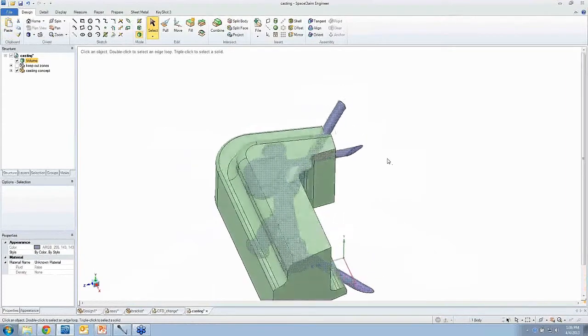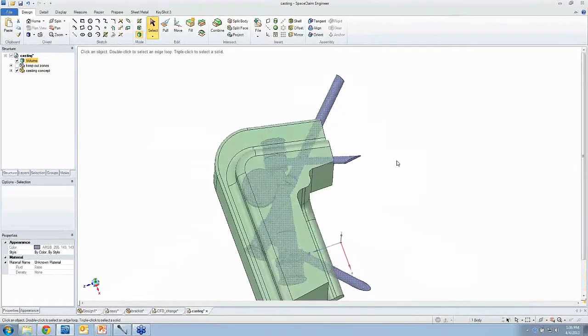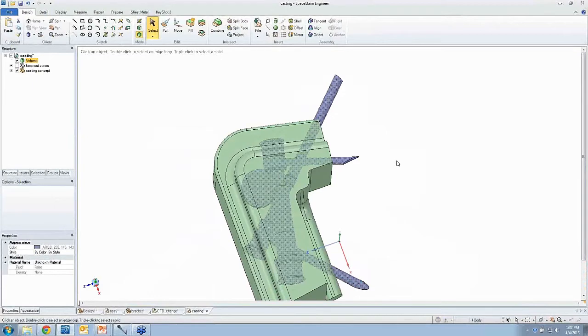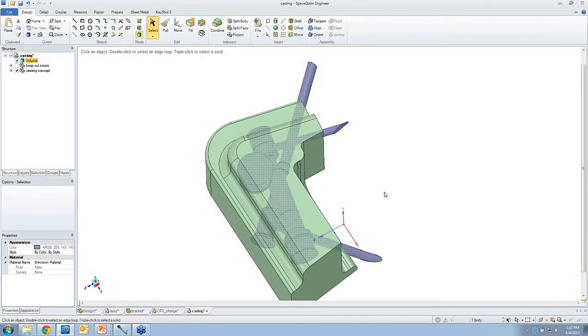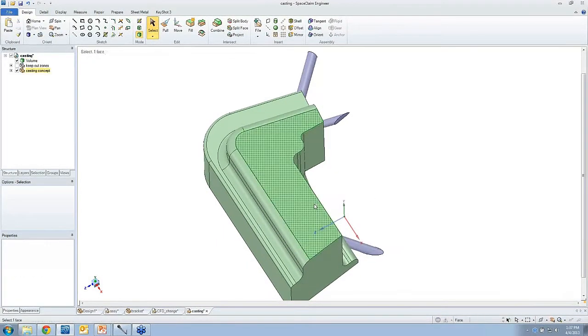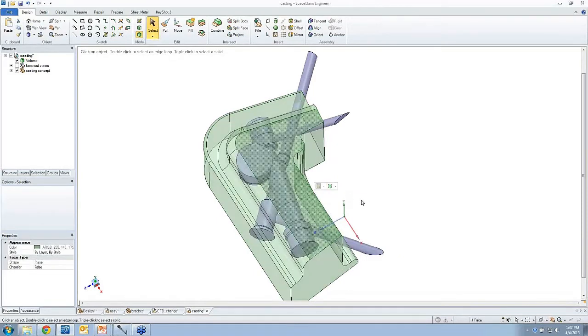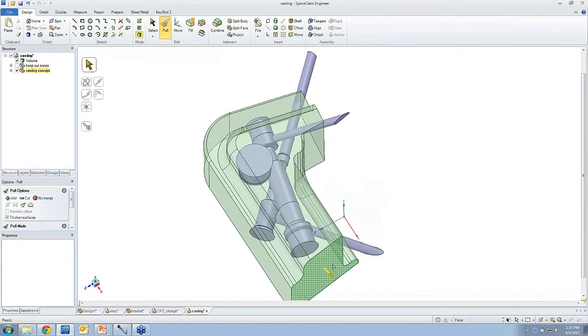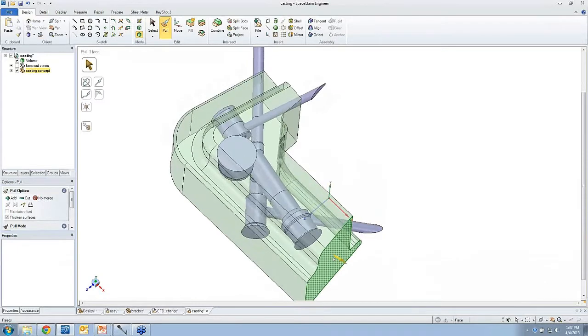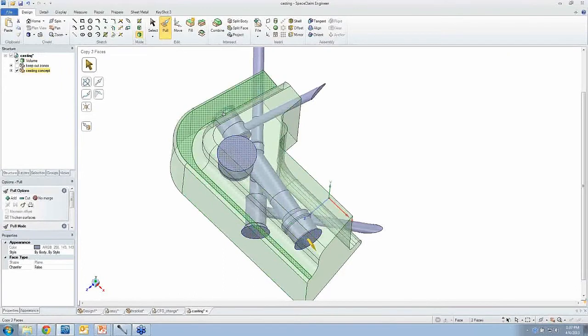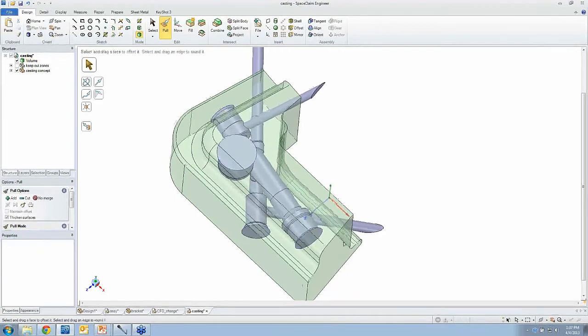Alright, so you can see the volume sitting inside of the solid. These are just two independent solids at this point. And how do I make sense of this now? Well, probably one thing to do to start would be turn this into a transparent model and start making modifications to it. I've counted 4 main ports. I'll select them all right now so you can see them. 4 main ports that need to have an opening, or the solid needs to have an opening available for all those. So that's where I need to start doing my modifications.